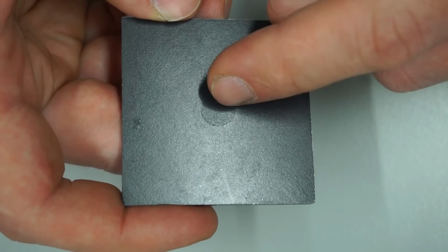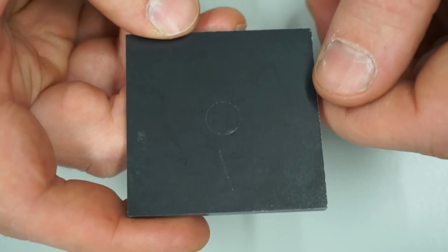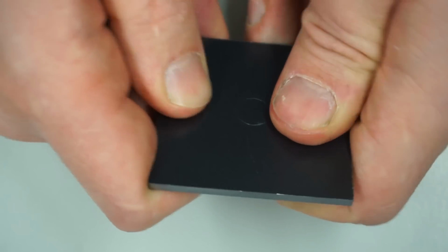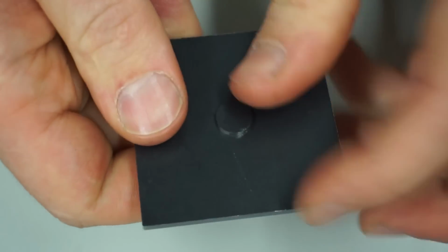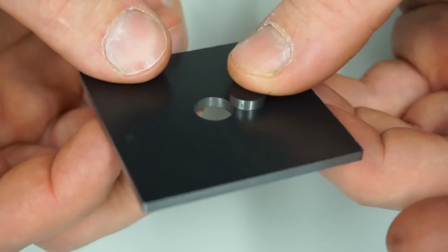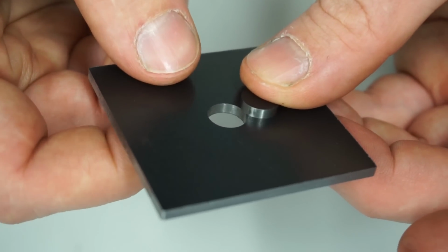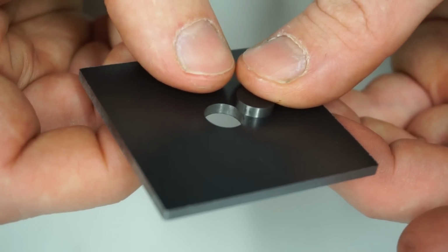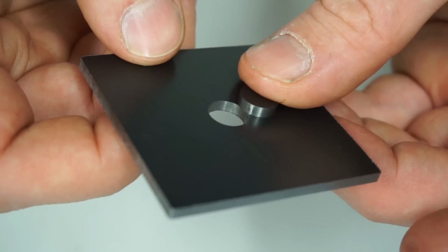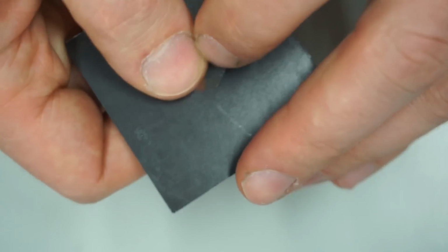For this we will heat the central spot of this 3 mm mild steel sample here, just like before. But other than before, the spot we will heat is actually a plug which very exactly fits into this hole in the sheet. For this experiment to work correctly, plug and hole must have very good surface quality and be burr and chamfer free.